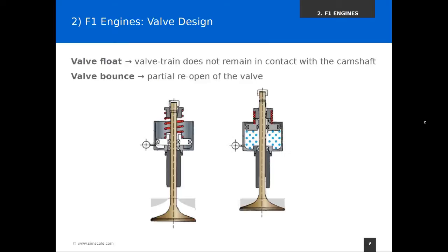Okay, now let's get a bit more specific. We'll be talking about valve design in this session. So let's just quickly take a look at these pictures to have a better understanding of an engine valve. The engine valve is a very crucial part in engine design because it has to keep the combustion chamber tight, so we must not lose any of the gas which should be enclosed there. But at the same time, they need to move very, very fast. So this is one example.